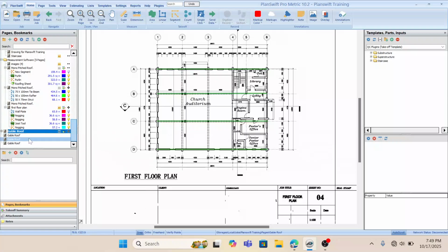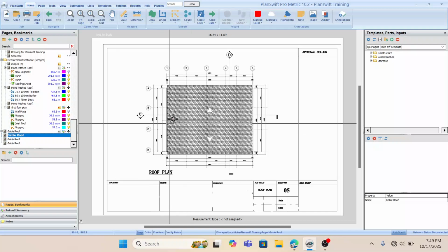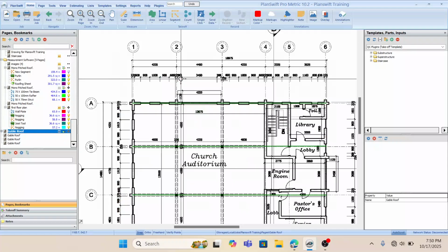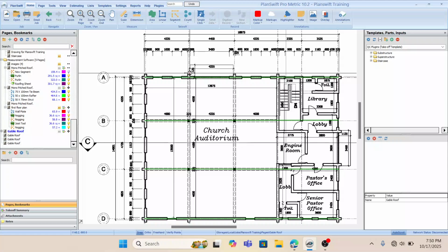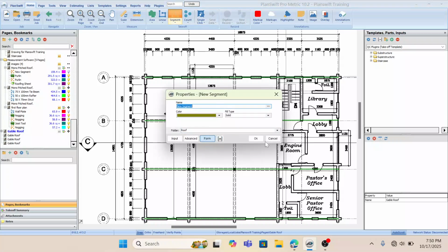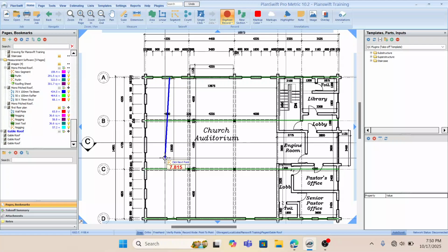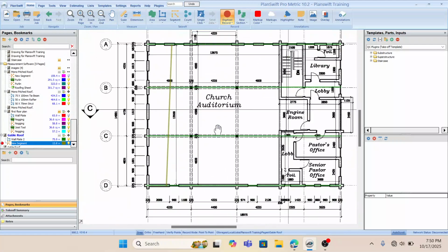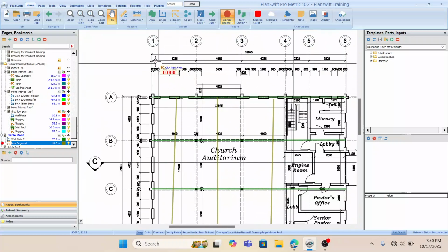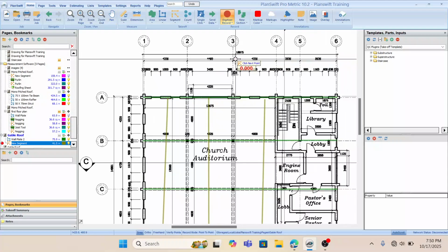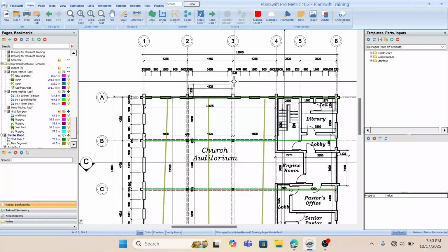Then let's measure other members. We're going to measure other members on the other drawing, not this drawing. But we need to calculate the number of setups. Since our spacing is 1.2, the arrangement will go this way. So this is our setup. I want to pick this particular dimension and divide it by the spacing to get the number of setups.